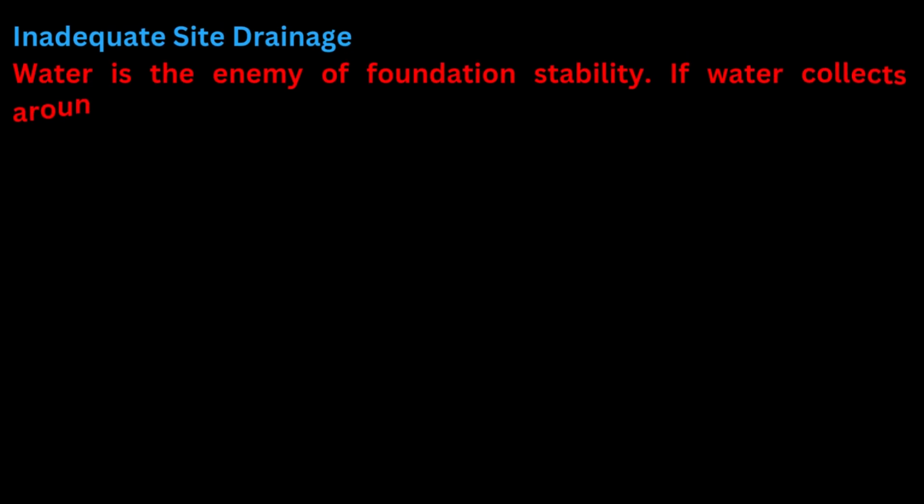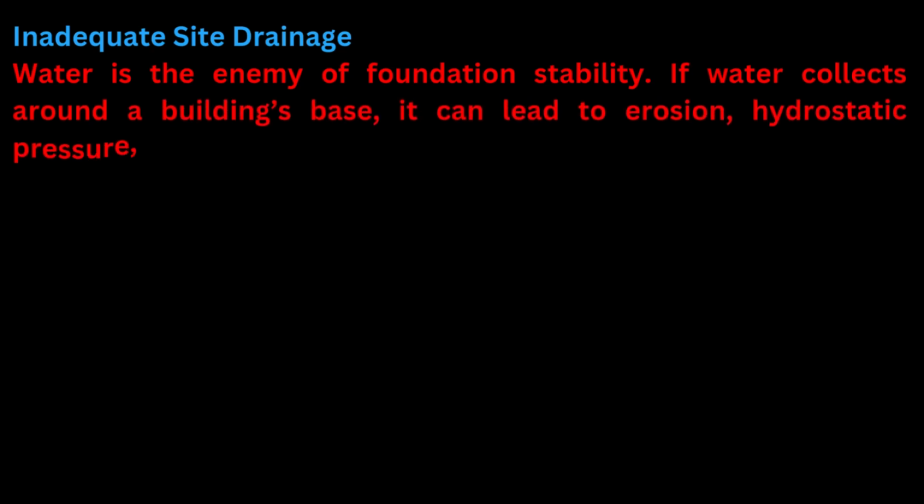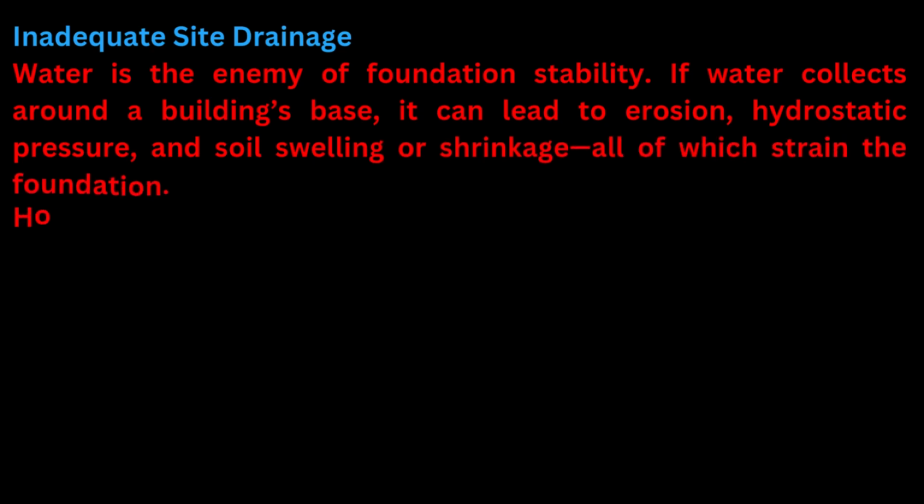Inadequate site drainage. Water is the enemy of foundation stability. If water collects around a building's base, it can lead to erosion, hydrostatic pressure, and soil swelling or shrinkage, all of which strain the foundation.